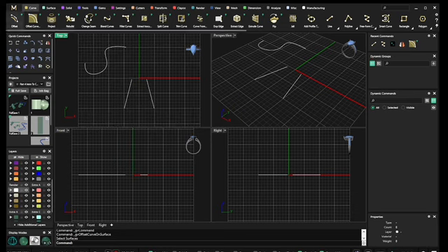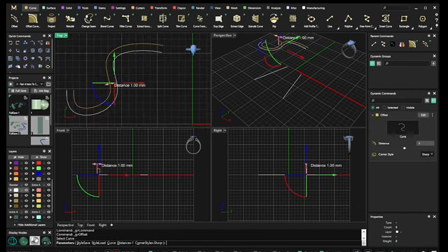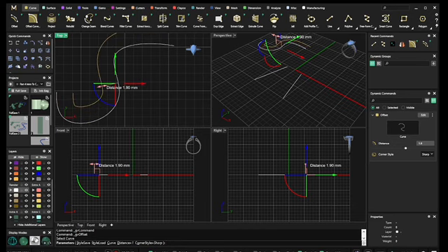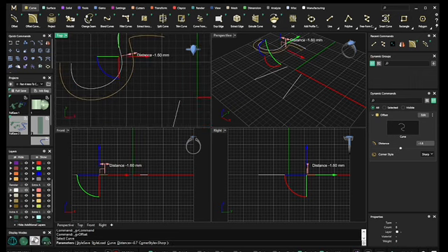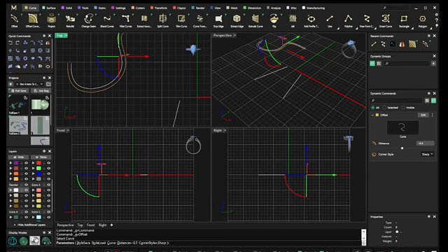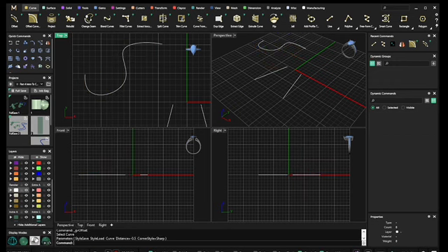Okay, offset. We'll do offset first. What you want to do is click offset, select a curve, because that's what it tells you in your command line. So I'm going to select this curve, and I can use these toggles to offset it and to see what distance it is. Now if I hold shift, it will offset it every 0.5. So there we go, there's 0.5. That's interesting. Oh, I've not used this offset curve before.